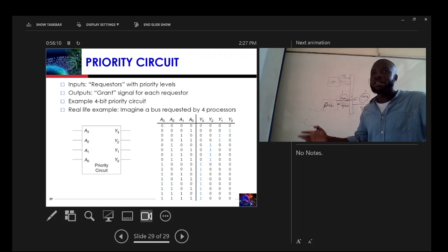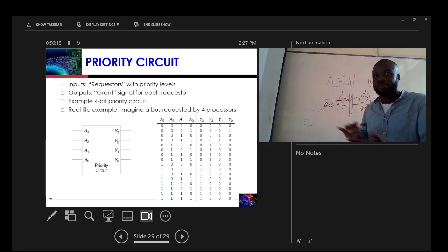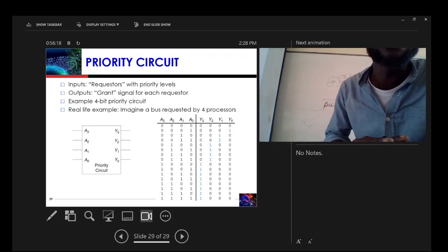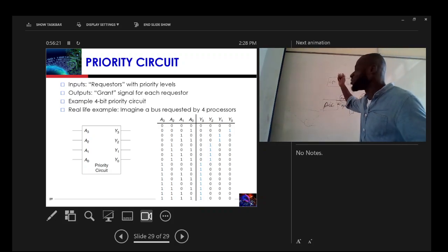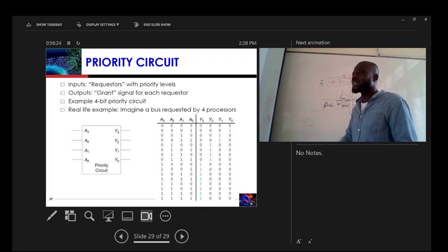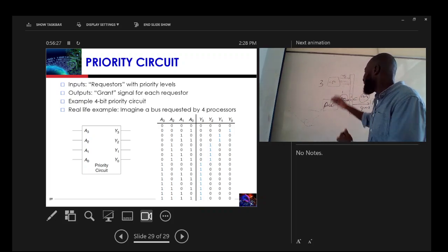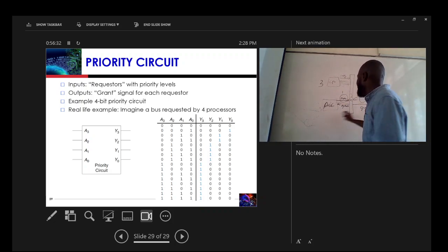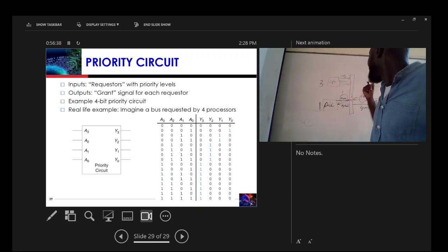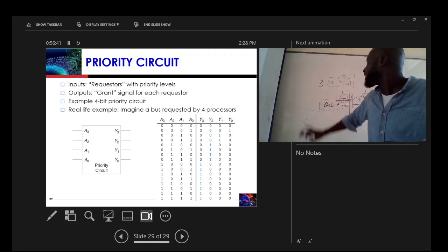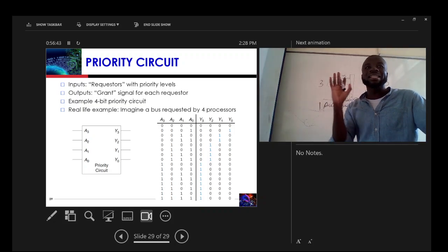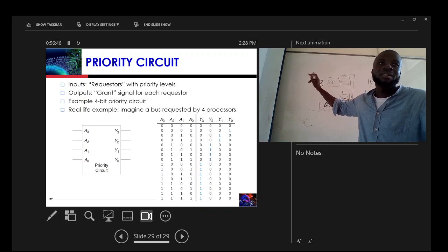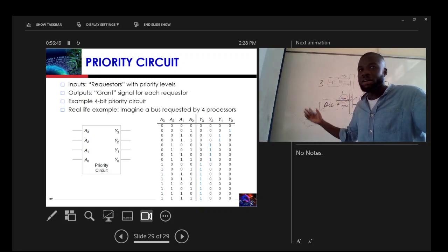So basically, before the chip is actually made, each component within your CPU's bus is given a priority. The CPU, of course, always has the highest priority, let's say three. Then the other components are assigned priorities: let's say two to memory, one to accelerator, and zero to IO. So if all the components request the bus at the same time, the CPU will be given the bus. Then the CPU must finish its operation before any other component can use it.